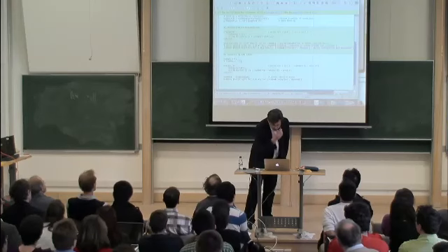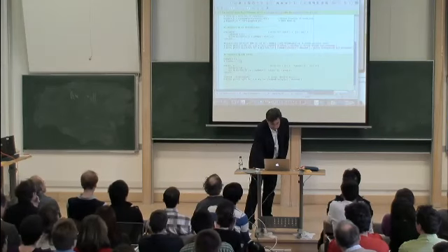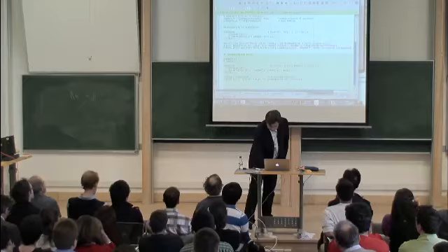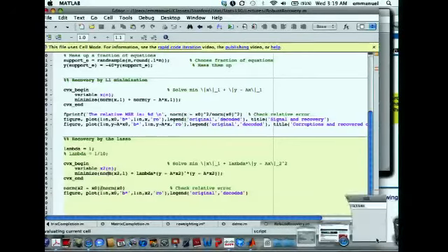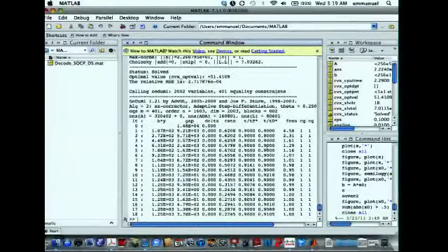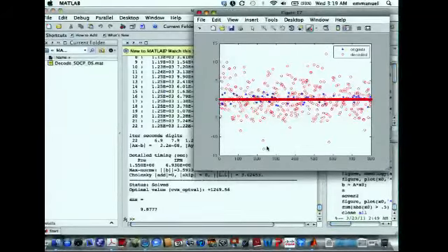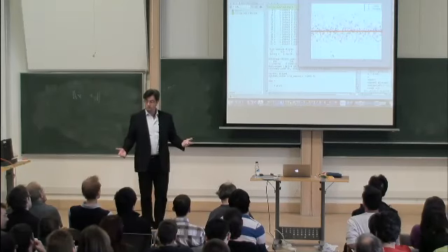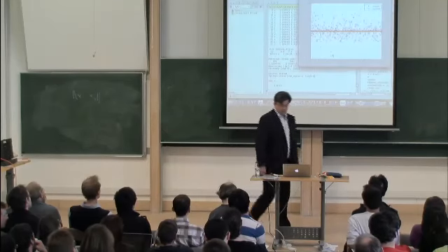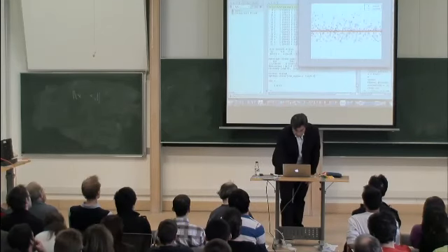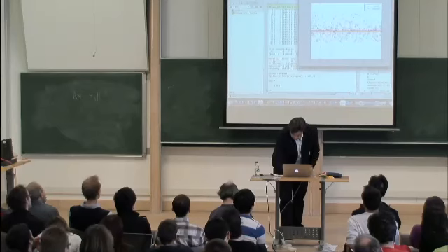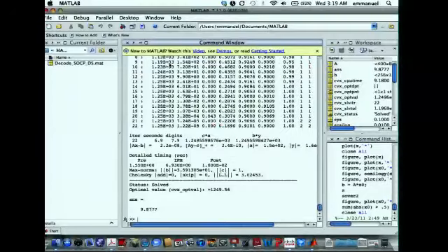Now if I recover it classically by the lasso, I'm going to get a terrible error. I get something that makes no sense, because the lasso is not designed to deal with impulse noise. It's designed to deal with Gaussian noise. So if I use the lasso to recover the signal, the fact that I corrupted a lot of y's makes the solution have nothing to do with reality. Now, how do you deal with impulse noise? That was a question that was posed to me during this lecture.